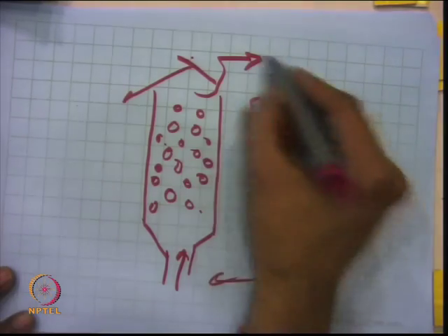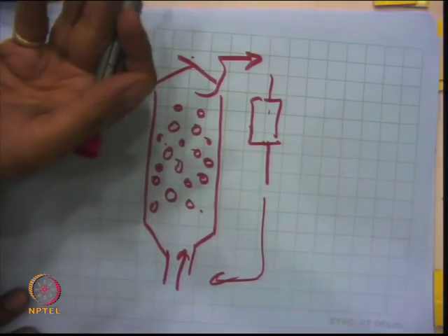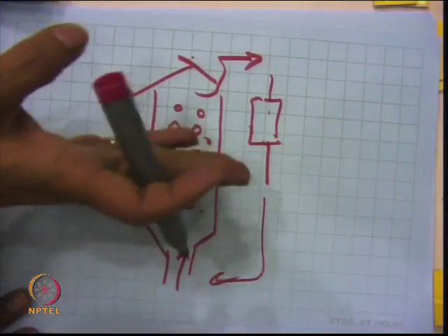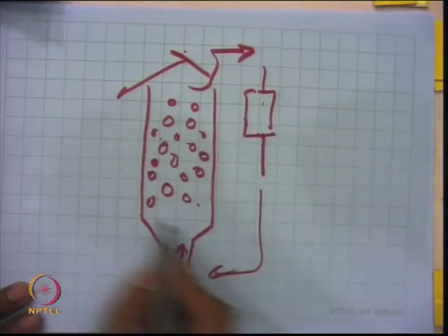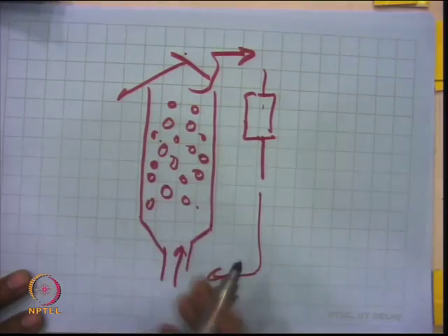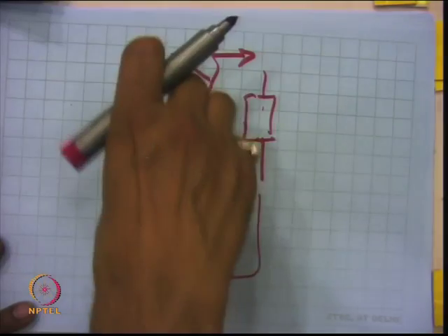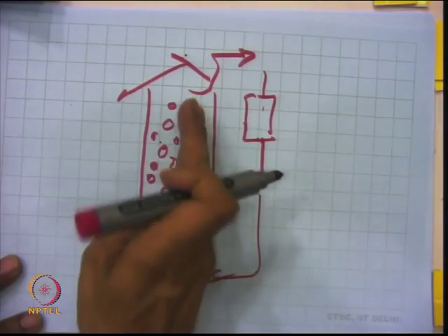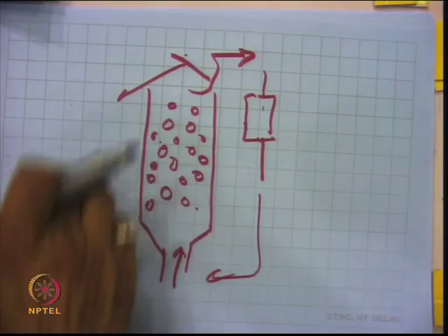So, in order to improve the conversion, if conversion is low, just like say coal gasification, it can be done in a circulating fluidized bed. So, then you circulate the gas again and again or coal particles again and again in the circulating fluidized bed. And the same thing I was talking about, if this is a catalyst here, then they are taken into a second system where you have a regenerator